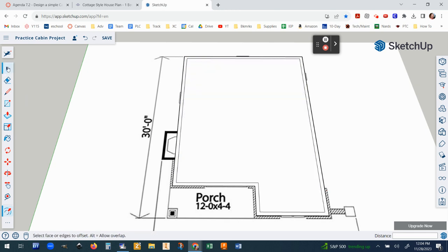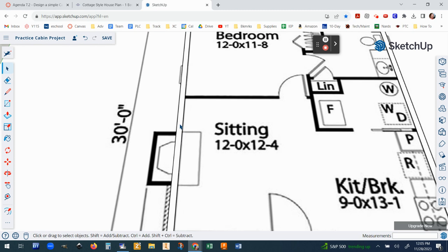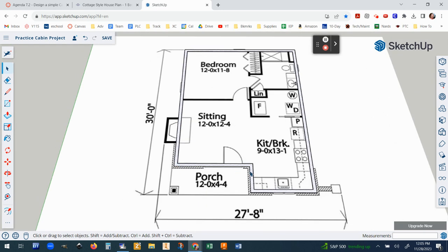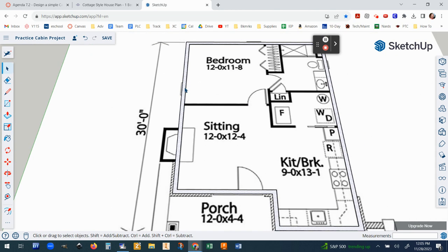Now, go to your select tool. Select that face in the middle, hit delete. Now I can see all my walls again. And yes, I actually want to delete the face that's been created between my lines. So that offset and my outside perimeter creates a face. I need to delete that because I need to know where all my window and door openings are.